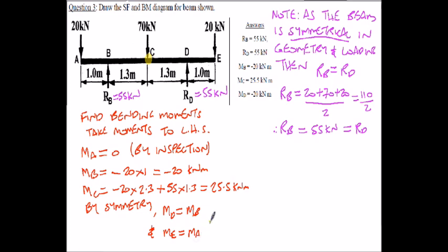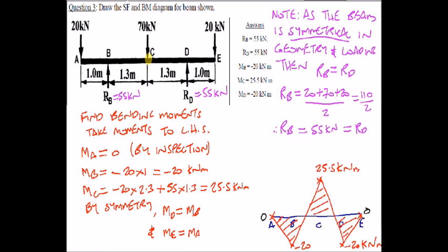So we've got all the points we need to plot our bending moment diagram, so we can do that now. So over here, put my beam, and as always we should title the diagram. This is a bending moment diagram, units, kilonewton meters, and again if we want to put the positive notation down for the bending moments. And there's the solution to that question with the bending moment diagram.